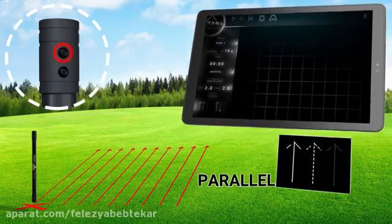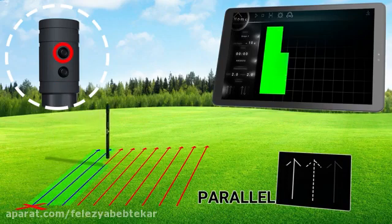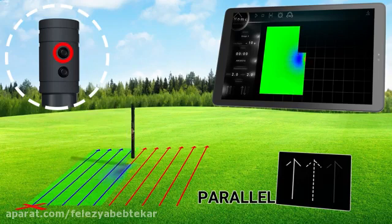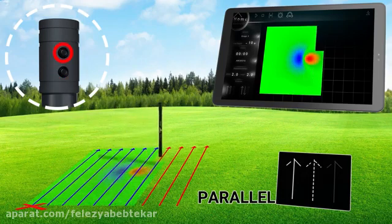The scanning process begins physically. It starts with holding down the data button. Note that when performing a unique scan, we must move on the marked lines at a constant speed and always keep the sensor at a 90-degree angle and a short distance from the ground.